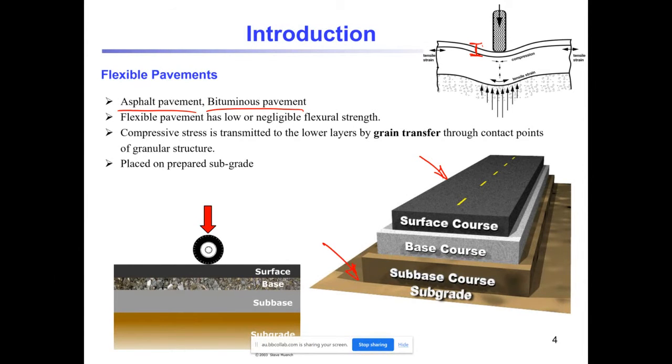We need to determine the CBR value for the subgrade or the Young modulus for the numerical analysis or for mechanistic design. If CBR is less than 5, we generally need to stabilize the material in order to improve the quality, in order to make the field ready for construction. And as I mentioned, almost all of the Australian paved roads have flexible pavements.